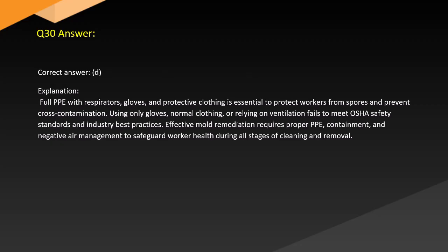Answer. Correct answer: D. Explanation. Full PPE with respirators, gloves, and protective clothing is essential to protect workers from spores and prevent cross-contamination. Using only gloves, normal clothing, or relying on ventilation fails to meet OSHA safety standards and industry best practices. Effective mold remediation requires proper PPE, containment, and negative air management to safeguard worker health during all stages of cleaning.